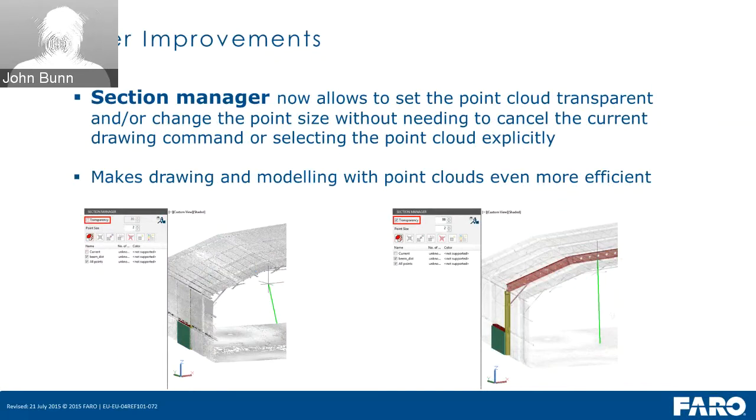And in this case, now all you have to do is set the transparency, and it'll stay at that transparency value even when you uncheck it. So if you set it to 60%, for example, and check it, you'll be able to see your modeling. Then when you uncheck it, the cloud will go back to its 100%, opaque view. But the next time you need to do the transparency, you don't have to set it to 60 again. You just put the checkbox back in. I'll show you a video on this. You'll see how much it helps.